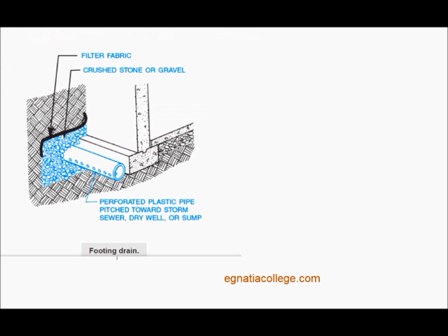Drainage. After the foundation walls are erected and before the excavation outside the walls is backfilled, filled with earth to the finished grade line, footing drains, if indicated, must be installed. Footing drains are usually perforated plastic pipe placed around the footings in a bed of crushed stone.